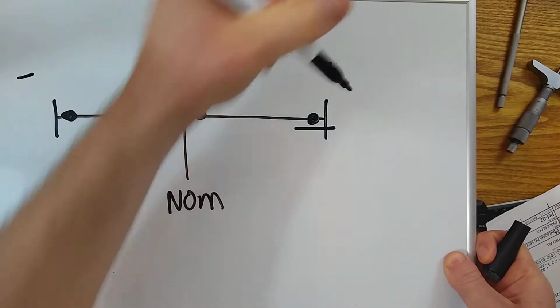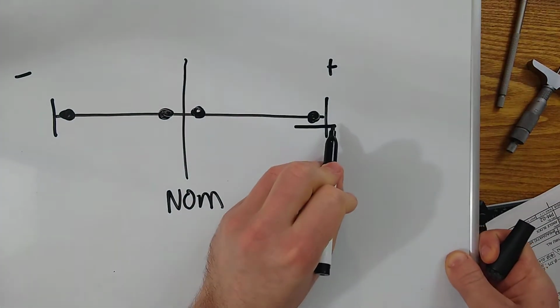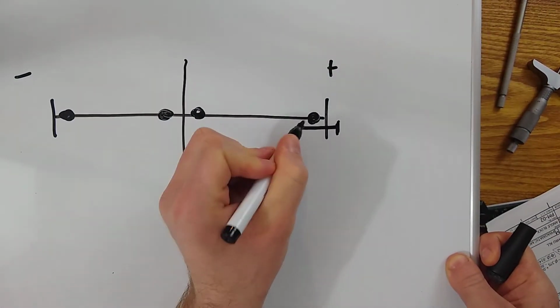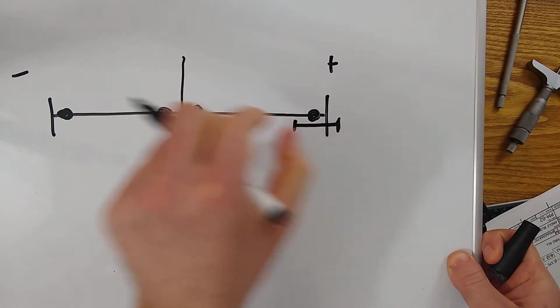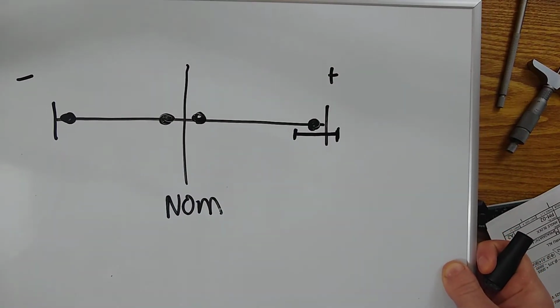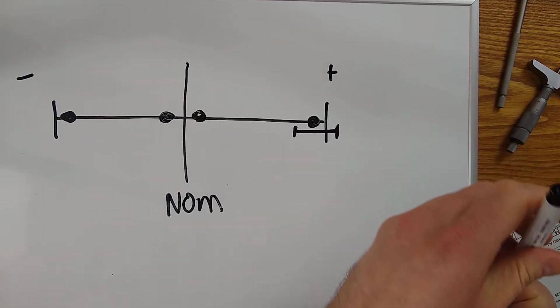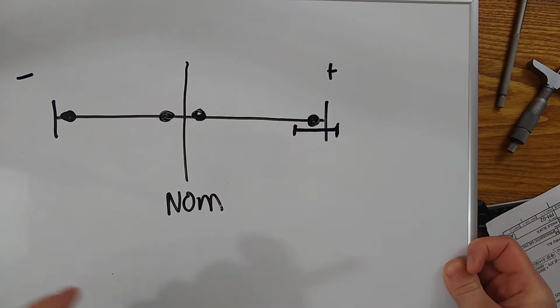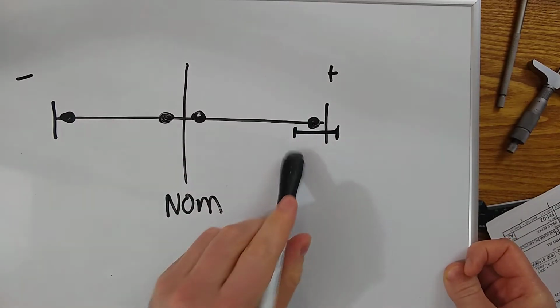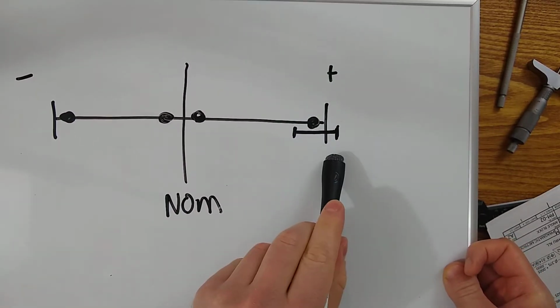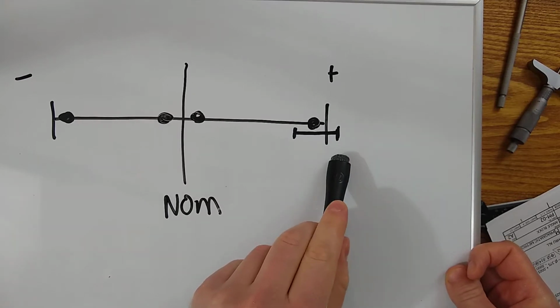There are a few exceptions, but in reality that part might be out of the tolerance zone, but the gauge has a little accuracy uncertainty, so whatever you measured could be in that range as well. So it might be out.